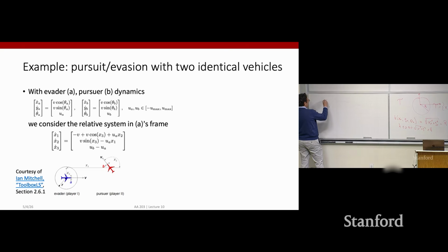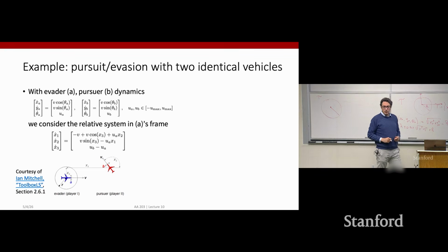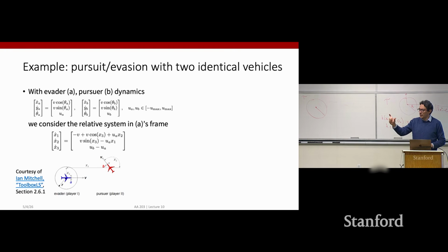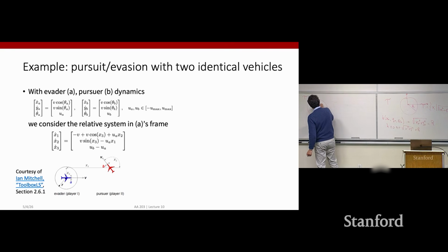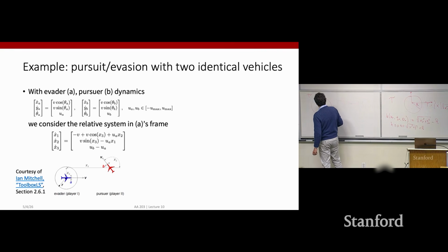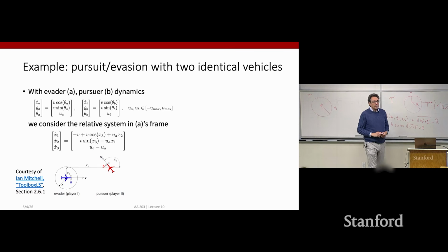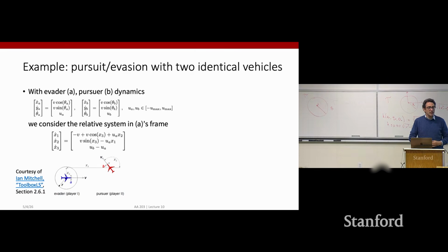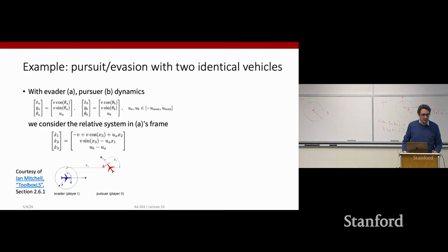So essentially, our avoidance set is indeed a circle in the relative position, x_a minus x_b and y_a minus y_b. We want the relative distance between the two aircraft to be less than r. So if we center everything around aircraft A, we want to make sure that B is never inside this kind of ownership circle. So what is the set of initial conditions that allow us to make sure that a collision, or at least a near miss, never happens?